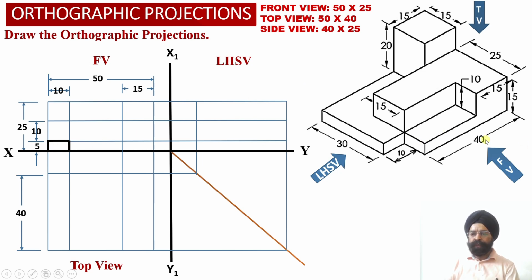Similarly, when the observer looks at the solid from the front view orientation, this L-shaped surface, which will include element number 1 and element number 2 over here, is again parallel to the vertical plane, so its projection onto the vertical plane into the front view projections will provide us the true shape projection of this surface.